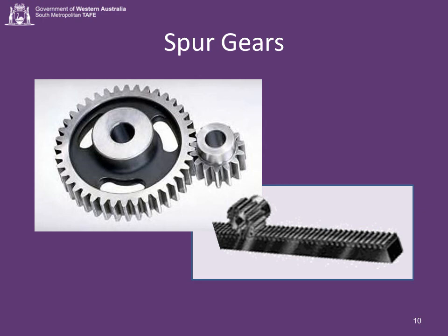It's a curve that is traced by a point on the end of a taut line unwinding from a circle. The larger the circle, the straighter the curvature, and for a rack, which is essentially a section of an infinitely large gear, the form is straight or flat. The generation of an involute curve is shown in the next slide.